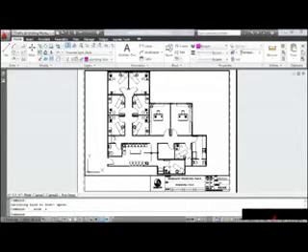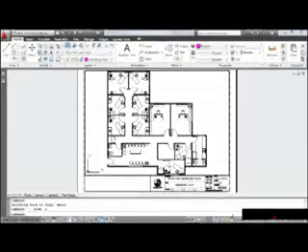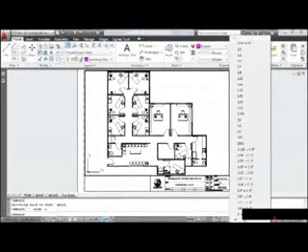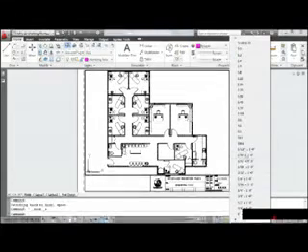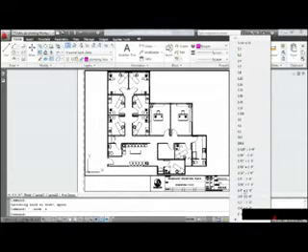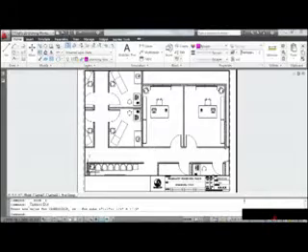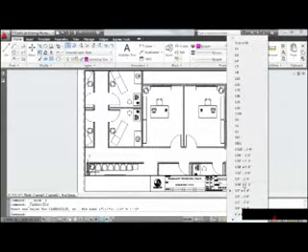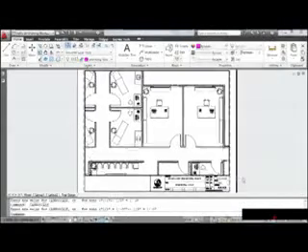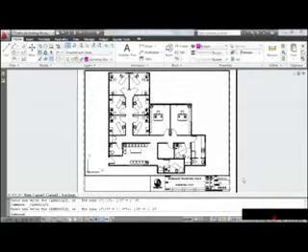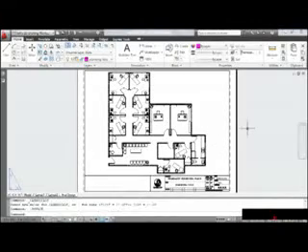The next step is to set this geometry to a measurable scale. I'm going to open up the Viewport Scale menu. And since this is an architectural example, I'm going to be using these scales at the bottom of the list. Let's try 1/4 of an inch equals a foot. It looks like that's going to be too big. I'm going to open up the menu, and I'll try 1/8 of an inch equals a foot. It looks like that scale is going to work perfectly. So I'm immediately going to come back down and lock the viewport, and then I'll jump out of the viewport by double-clicking outside the viewport boundary.